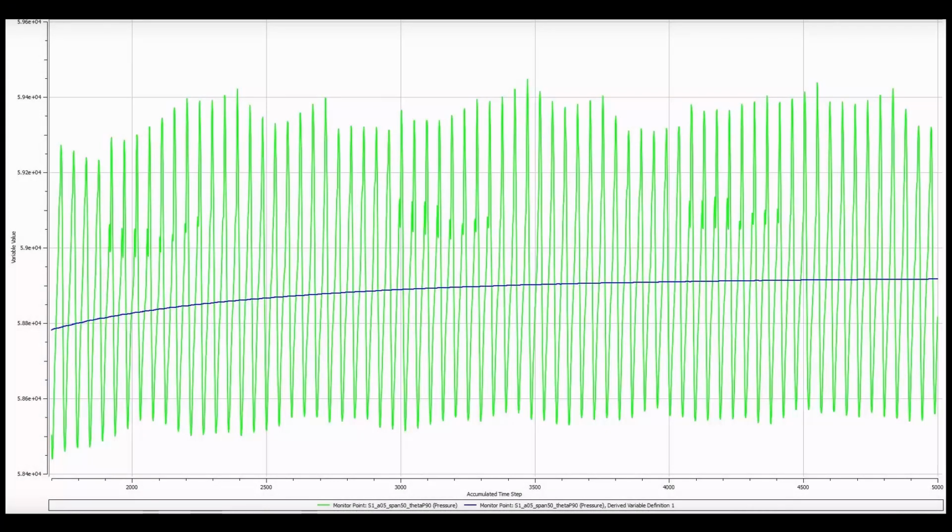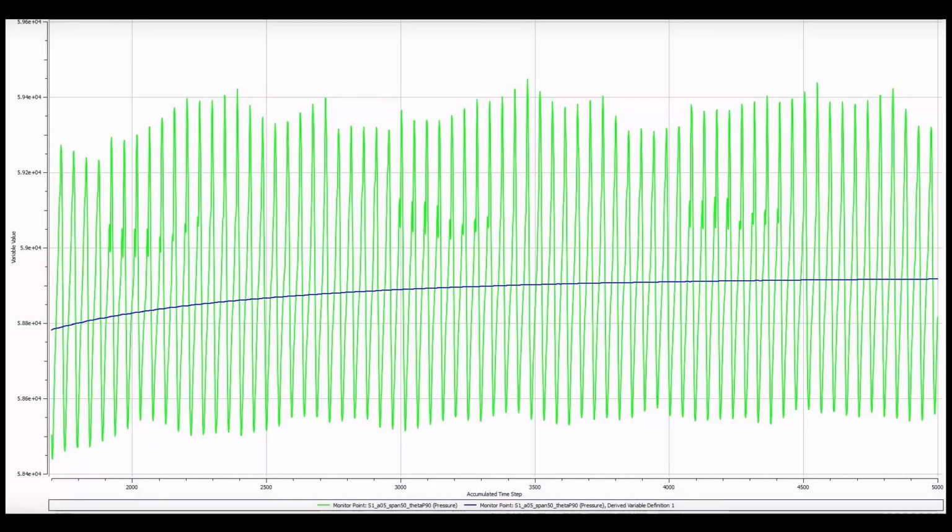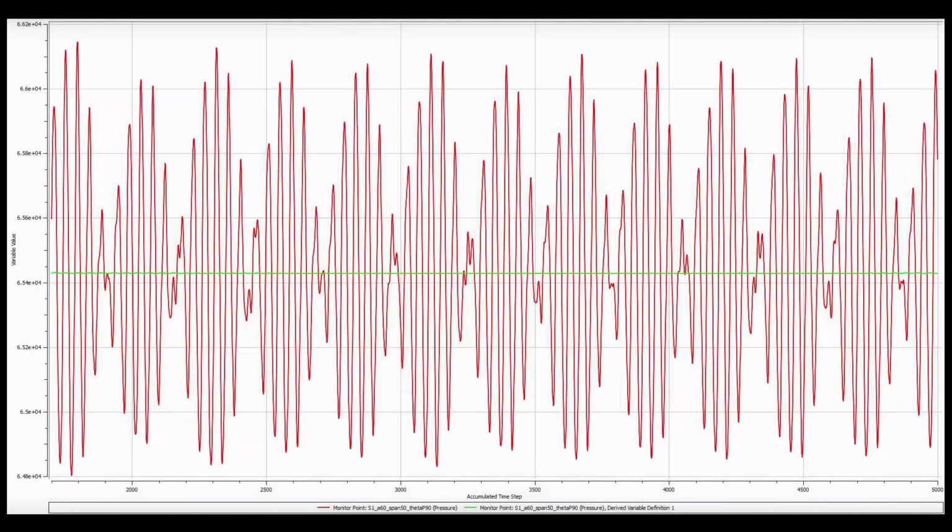This plot shows the pressure change at the inlet of the stator as rotor 1 rotates. As we can see, 23 pulses have been captured over a single full wheel revolution, corresponding to 1 complete rotation of rotor 1. The monitor at the center of the passage shows an interesting result. Here, we can see more complex signal structure due to the interaction between the front rotor wake and the back rotor potential field. This result conforms with expectations since each rotor demonstrates a different passing frequency.